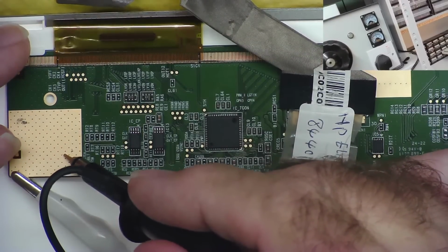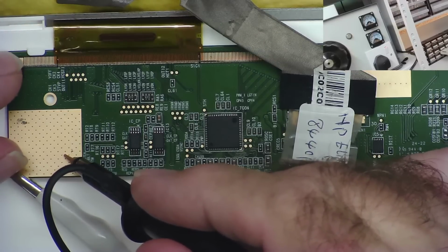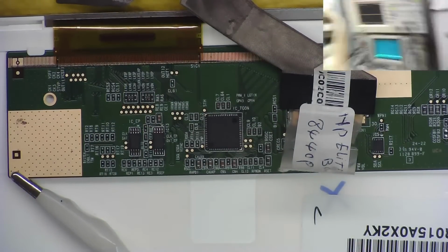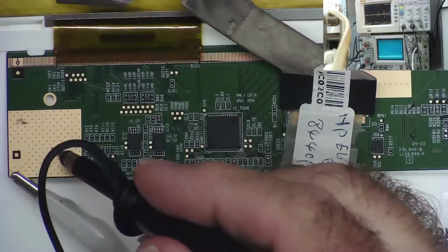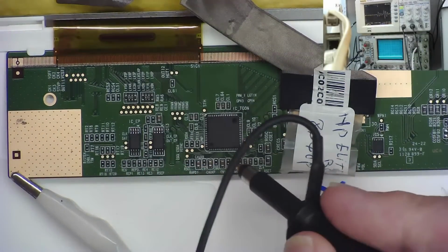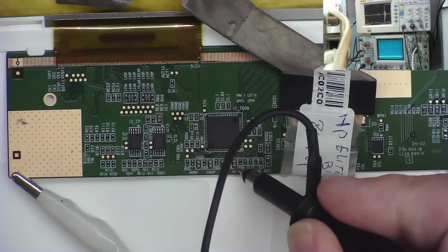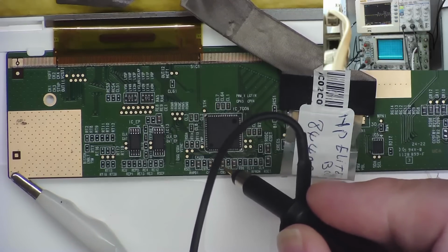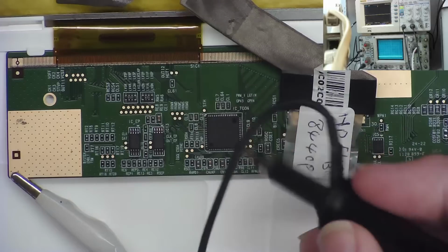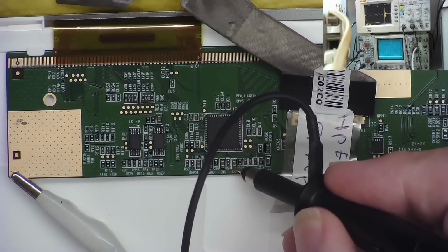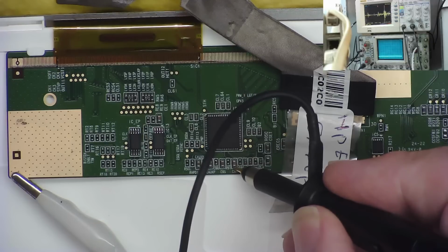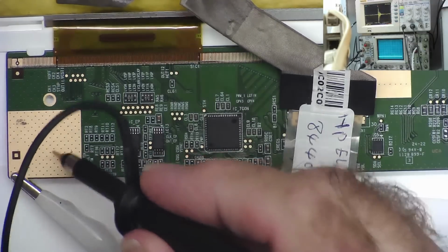I'm getting that much noise on the ground now, if you can see that on the oscilloscope. Oh, the oscilloscope camera's moved. Okay, so if I just get this thing to stay still. I'm on the very sensitive setting on the scope because I can't see much of a signal on these, and I'm just picking up noise. Probably these LVDS signals are extremely small level signals, and I think they're going to be very difficult to see if anything's actually on them or not. There seems to be something moving. It's possible I have a signal there, but it's hard to determine because there's so much noise. That's on the ground.